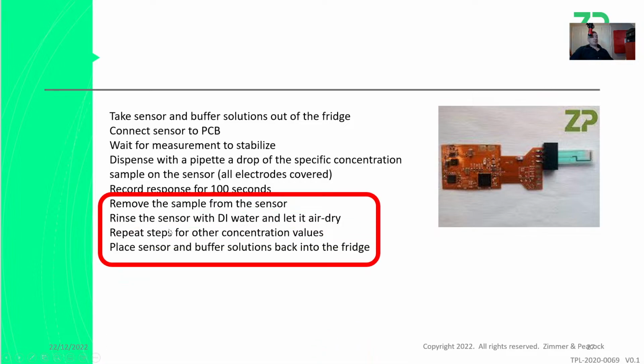Removing the sample, DI water, letting it dry: every time you use a glucose sensor, it can pick up history effects. So you're basically testing, picking up a history effect, testing, picking up a history effect, testing, picking up a history effect. When you look at Dexcom, Medtronic, and Abbott, their sensors go into that liquid and they stay there. They're not coming out and going back in again. So that's the first thing to note. I have no problems with it, and your data actually makes a lot of sense, but it makes sense in the way that you're testing that sensor.